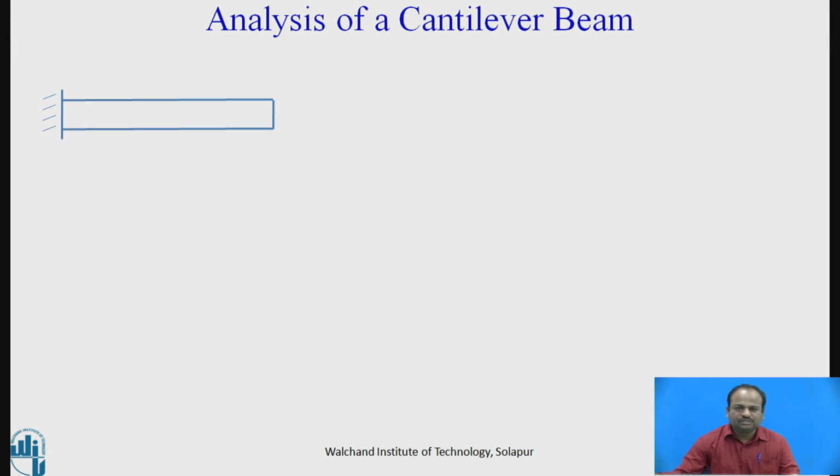beam. This is the fundamental thing. Once we know how to calculate the beam strength of this particular cantilever beam, then we can calculate the beam strength equation for the spur gear. So this is the beam which is having a length. This is where the tangential force is acting. Now that tangential force is Pt over here.